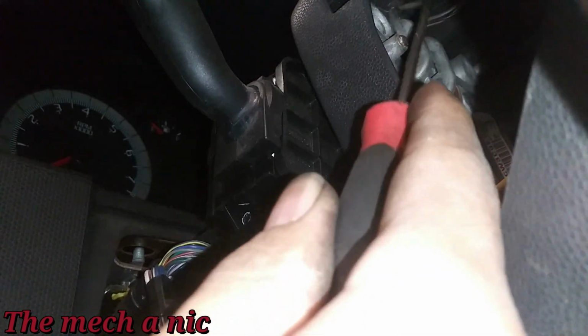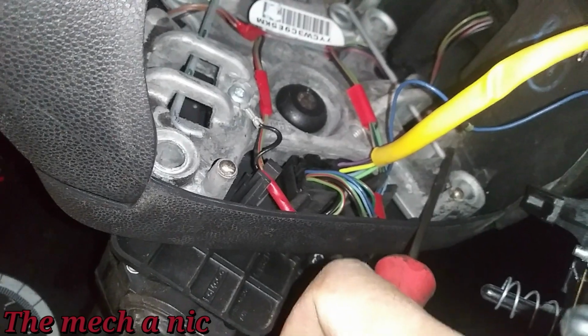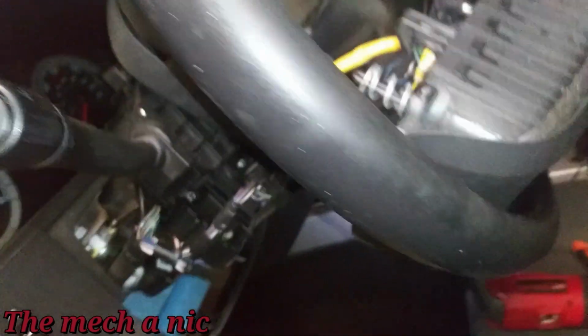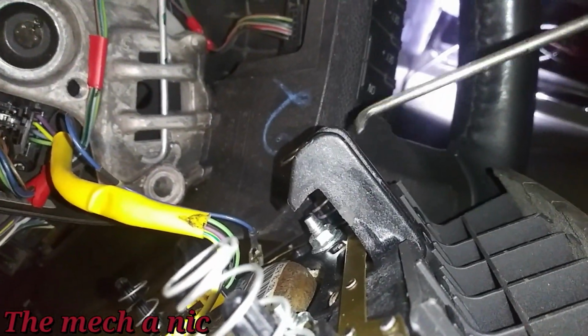Pull this spring, and this end of the airbag is going to pop out. And then same thing over here. You come over here, you pull this spring. It's hard to show you guys, my hand is in the way. Basically, you're going to come in here, pull this spring, right? And then this side of the airbag is going to pop out. So at this point, you're going to have this one and this corner disengaged already. The only thing that's going to be holding at this point is this center piece right here.